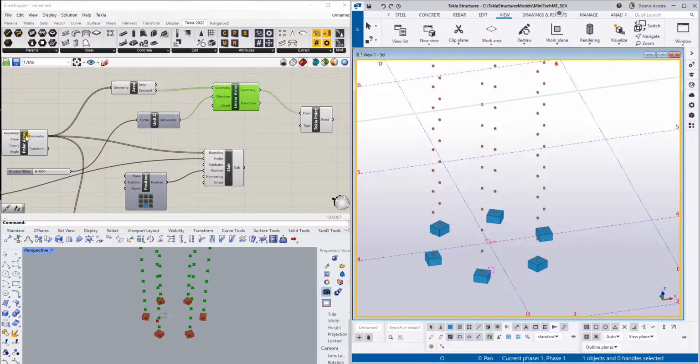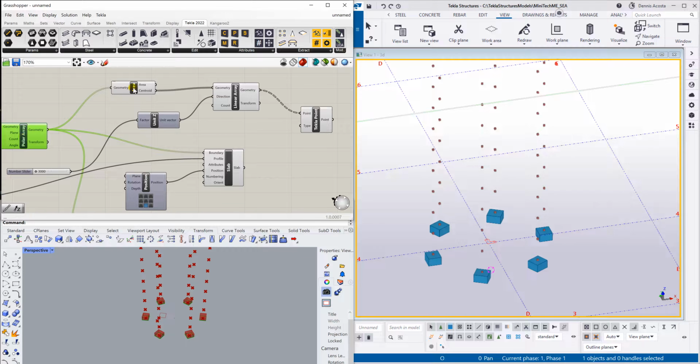Okay, again, from the polar array, you link that, you create an area, and then get the geometry, and then under the area, you can see the centroid, and then link that one to the linear array, and then control the direction. Okay, so this one is the direction. And I guess we need to also add the count here.